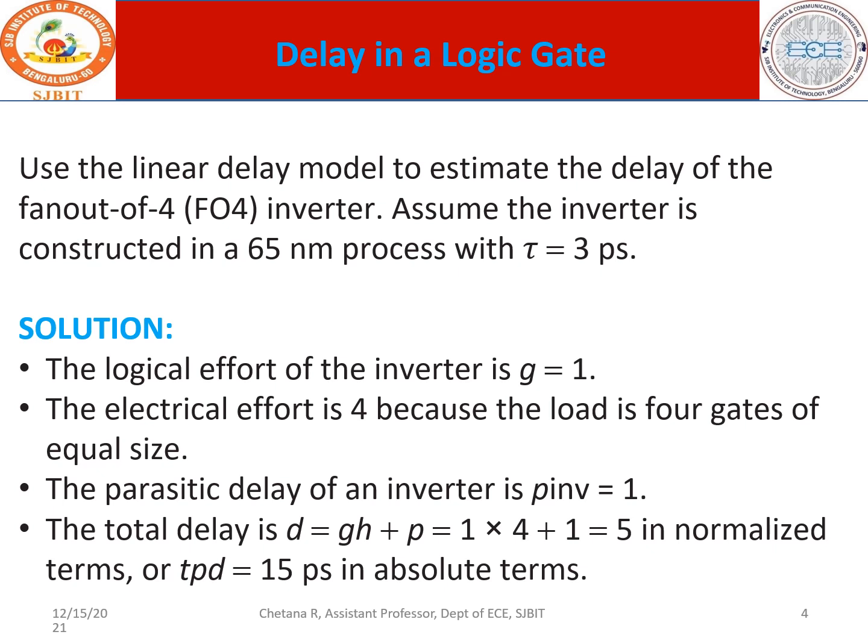We have just now found out that a unit inverter is of size 2:1, and therefore, combining this, the input capacitance is 3, and the output inverter capacitance together, which is nothing but the drain or the diffusion capacitance, is 3. 3 by 3 will give you 1. Therefore the logical effort of an inverter is G equal to 1.